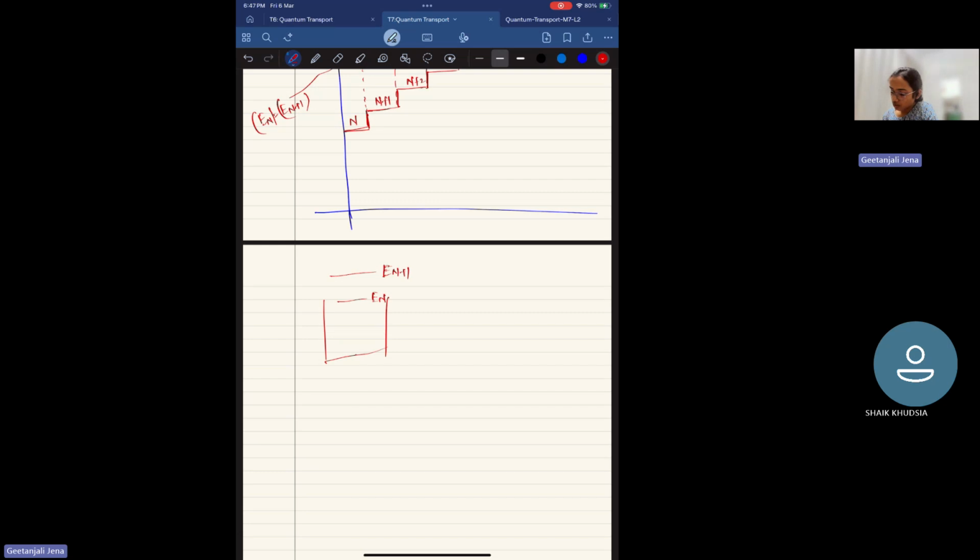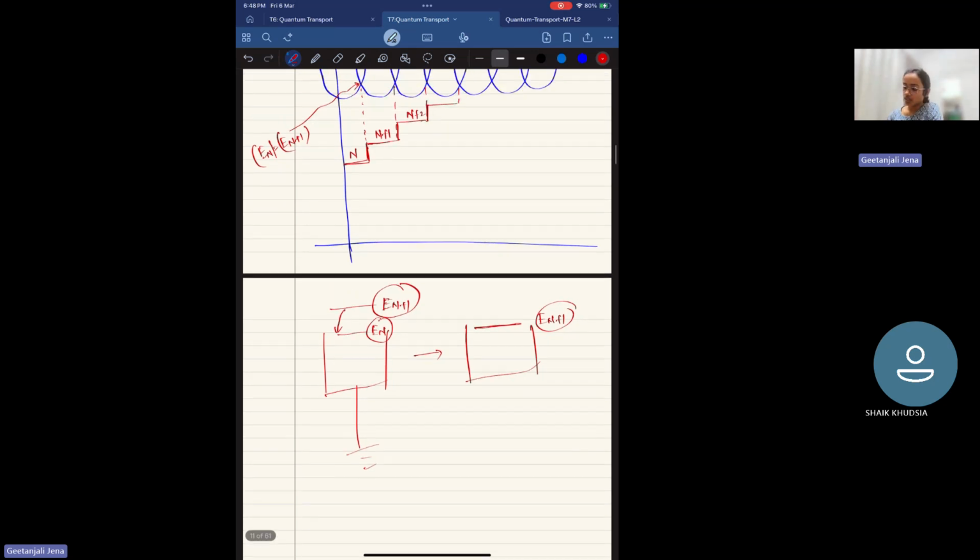But now, through this gate voltage, we have lowered the energy of this quantum dot region. So now the En plus 1 which was higher earlier matches with the energy of this En level. So it lies here. Because of this proper energy alignment, it's now possible to tunnel and add one electron to the system, because the energy is lowered by means of the gate voltage.